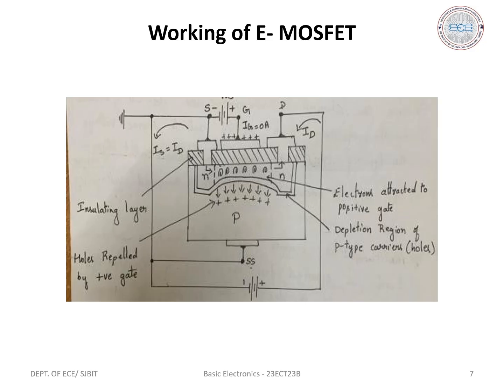When the value of VGS is greater than the threshold voltage VT and VDS is equal to a positive value, then as we increase the value of VDS, the depletion region also increases. As the depletion region increases, the channel width will decrease. Okay, so this is how the E MOSFET will work.